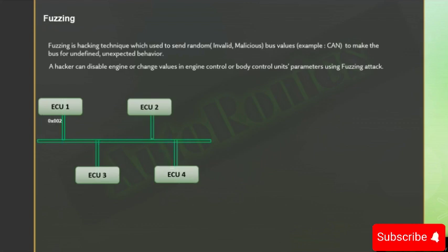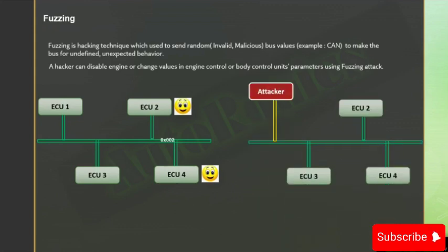This message will be sent out at a proper periodicity, at a regular interval, and it will be available in the bus. Whenever ECU2 and ECU4 need this message, they can subscribe and work on the functions that are needed based on the message. Yeah, this is a normal scenario. Since the messages are available at the right time without any faults, ECU2 and ECU4 will be happy to read the message as there is no confusion.